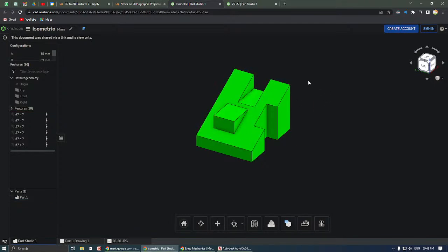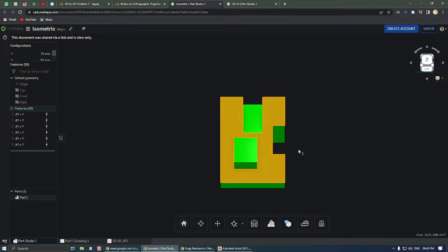We need not draw these things, because in the question, I will be asking only for the true shape, the area of the true shape, and the true shape is only this face which is highlighted right now. So all these extra edges coming up over here, even though technically they must appear, we are not interested in them, because we are interested only in the true shape of this particular face. So everything else that is coming, we have to ignore.